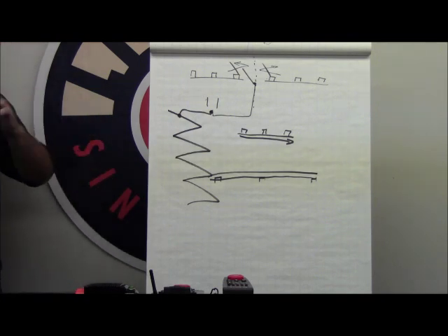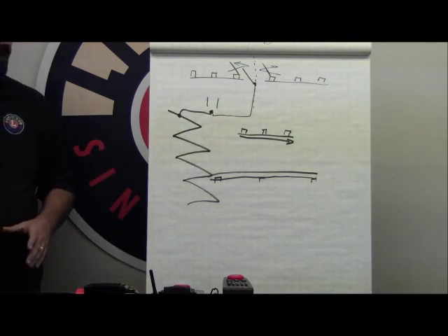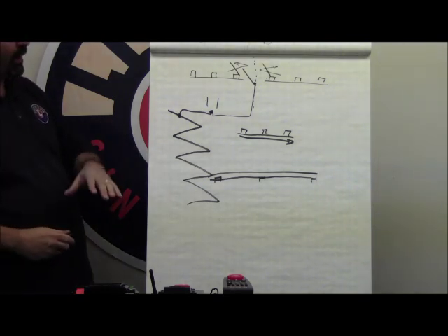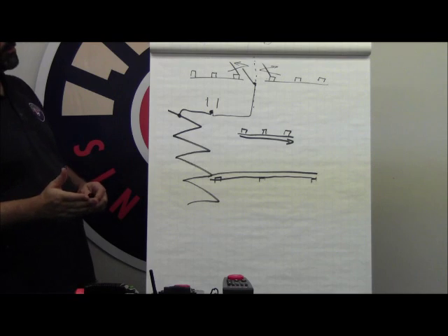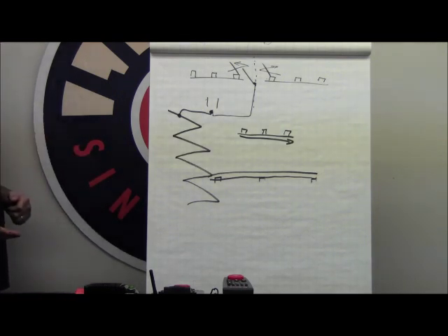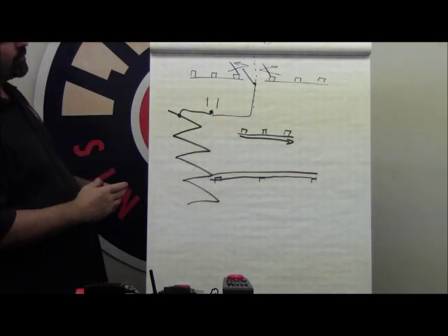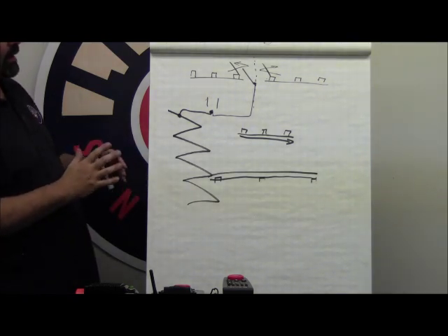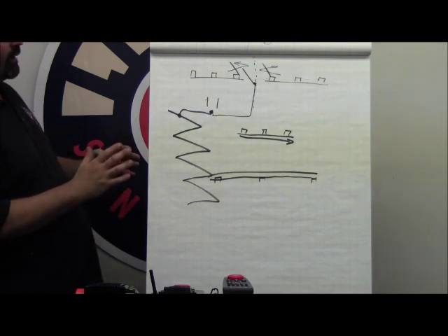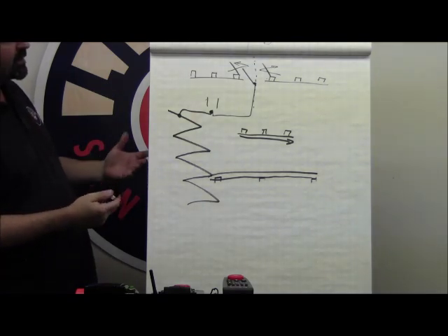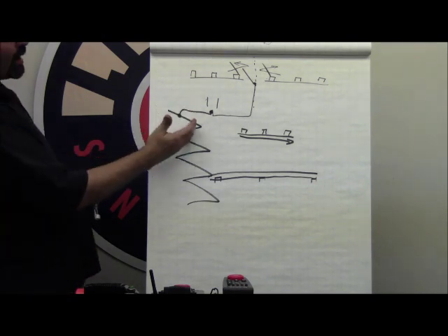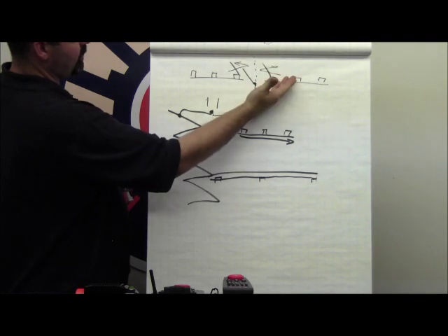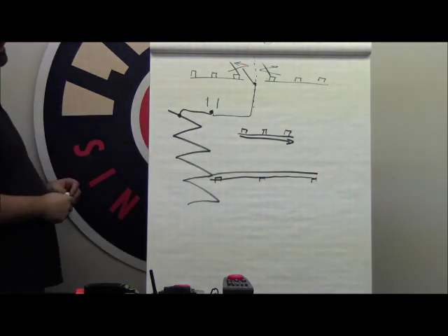I'm not saying that when you build a railroad you will have these problems, because every single layout all over the country differs and it varies. But depending upon the environmentals of your railroad, the wiring of your railroad, etc., you can have perfect command signal, or you could have a layout that has a couple of plagued areas where you have poor signal reception, or you could have several. At the end of the day, the ground plane is how you prevent that crosstalk of signal from affecting your operations on your railroad.